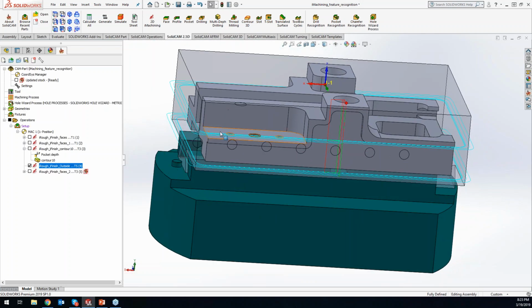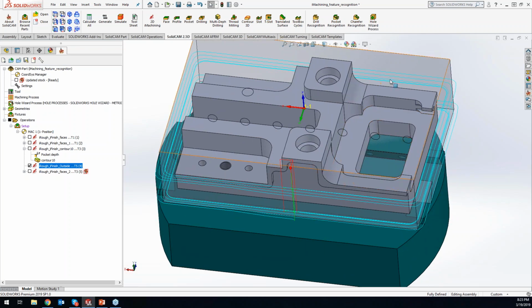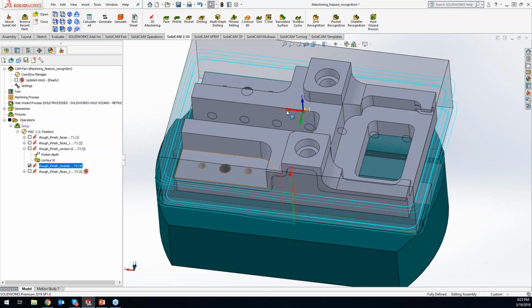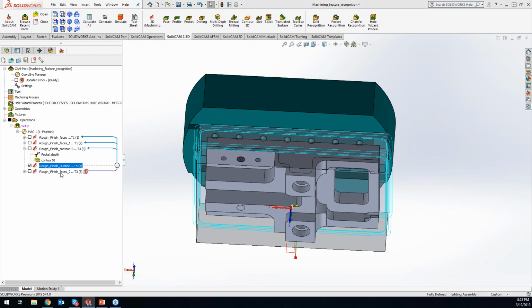Okay. So now that we've got the outside perimeter machined up here, I need to flip my part up on the side, and I'm going to do our single line geometry. So we'll do another 2D iMachining here.